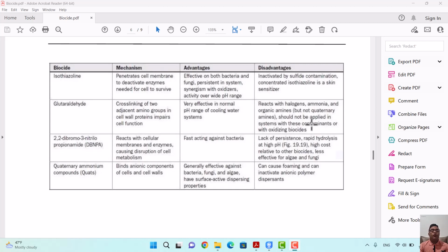And after 1 week, they changed the non-oxidizing biocide for their systems to isothiazoline, and after 2 months of use of isothiazoline, its activity against that bacteria was laudable, really amazing. There was no fungi, or let's say those green substances, on the walls of the cooling water systems, and everything was clean and neat.